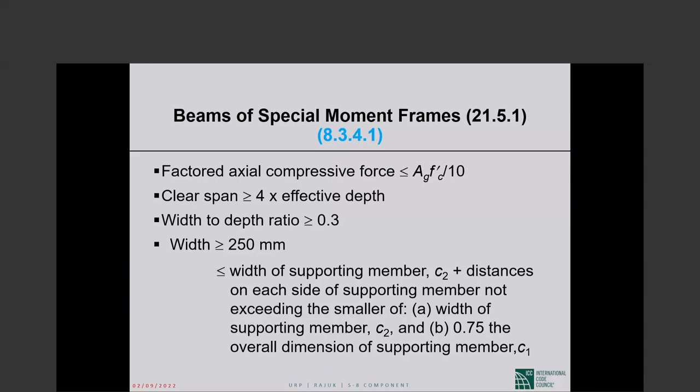In ACI handbooks, flat plate example, there is a minimum unbalanced moment, a function of dead load and live load at subsequent panels. That is added with the 1.2D plus 1.6L for punching shear calculation. We don't see it in your slides. Do we need that?